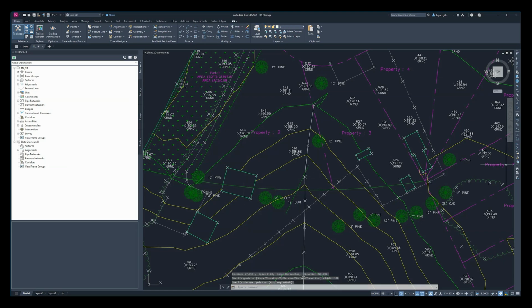Other option would have been to hit escape. One thing to point out, I say hit escape a lot of times, and what we're doing here is creating a polyline, or segments, at a time. If you hit escape before you were able to get that first line drawn where it's shown, it wouldn't draw anything for you, if that's not obvious. Just to make sure that you're aware of that.